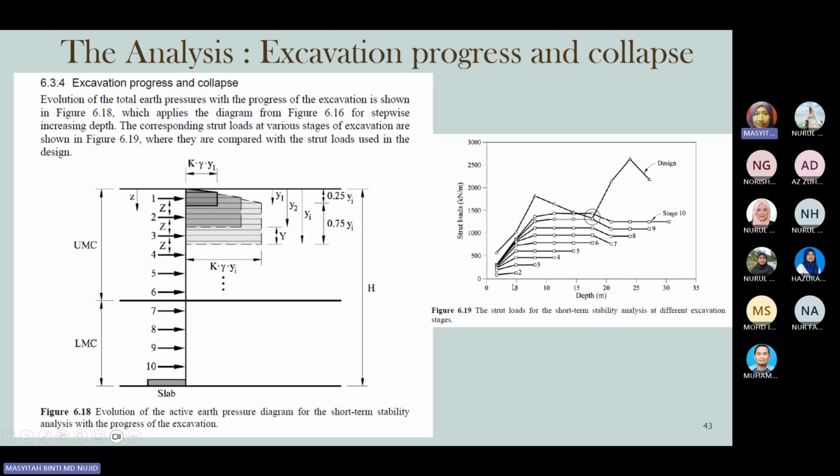How do the strut load forces change according to the depth? You can see that when the depth increases, the strut loads theoretically also increase, but it also increases by the stage of the construction. From the first stage of construction, stage 1, stage 2, 3, 4, 6, the depth of the strut load from the ground surface to the final strut load are totally different.